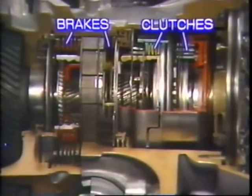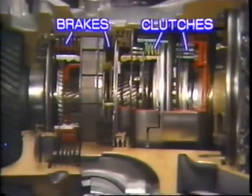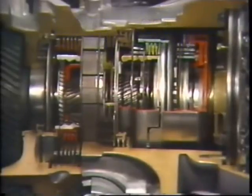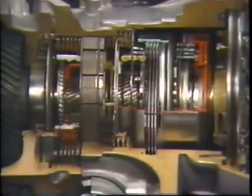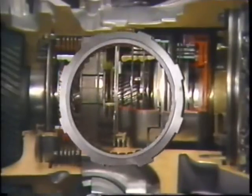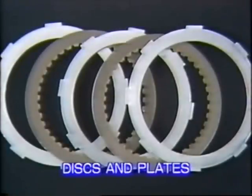The clutches are used to determine which gear will be allowed to rotate to actuate the planetary gear, and the brakes are used to hold particular gears so they will not rotate. In most models, wet multiple disc type clutches and brakes are used.